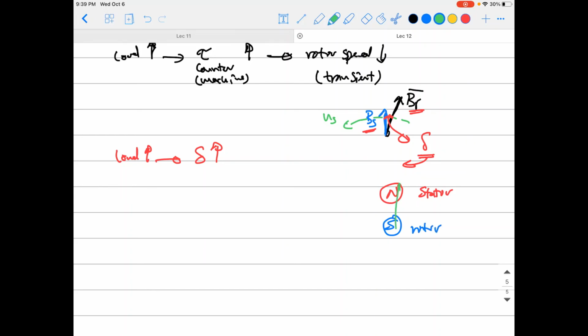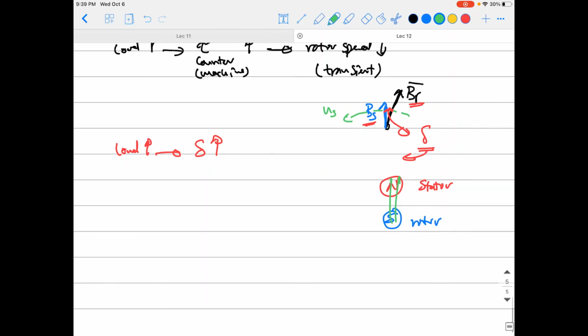And they're still coupled together by just magnetic attraction, a north pole attracted to a south pole, and they're still rotating together in some space. This was delta equals 0. But as delta has some value, that means the load goes up, and you'll just have some deviation like that. The north of the stator is here, and the south is there. They are still attracted and still rotating together, but now you have an angle between them.